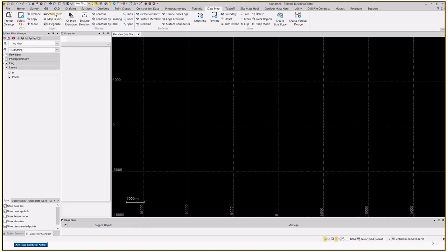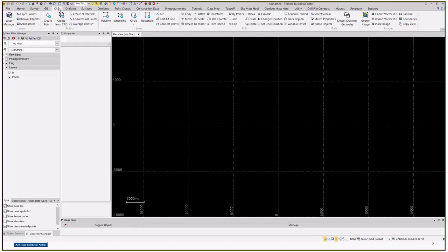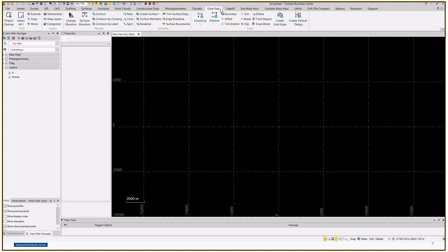And then we move into layering, customization. I mentioned those mappings of layers before, sits in here. Elevating our information, bringing it up to DTM, or up to the design. You can bring 2D information up and manipulate it that way. Creation of surfaces, and then some of our line information, which is very similar to what you would see in the CAD tab. So as in Trimble's world, there's some stuff in this tab that is somewhere else as well in TBC.